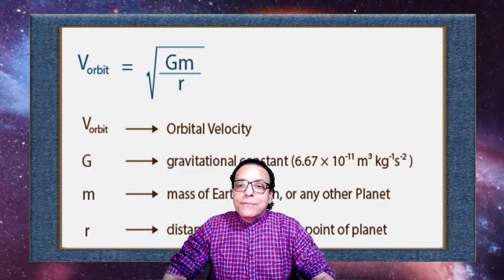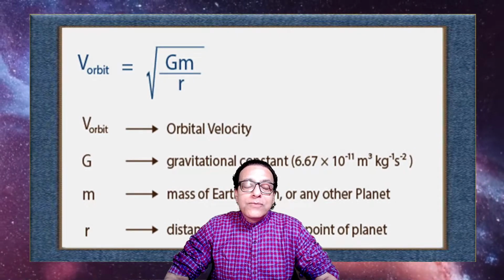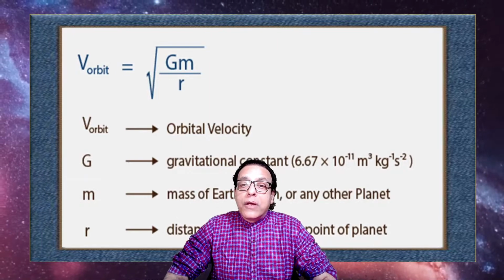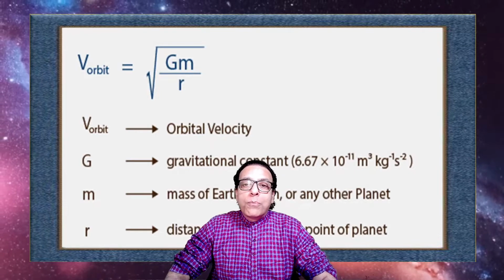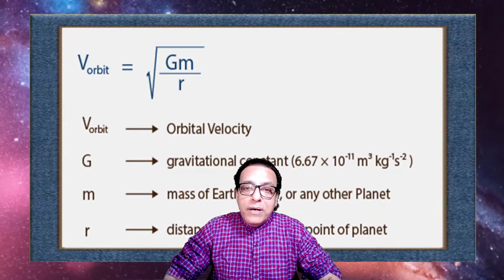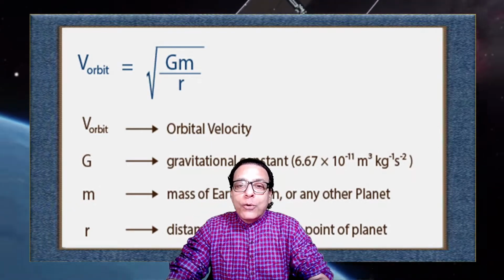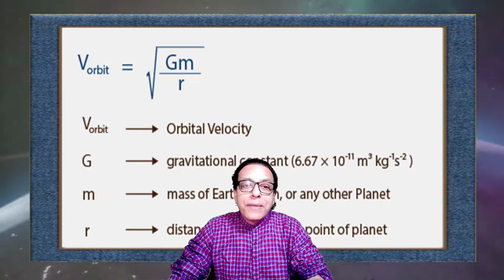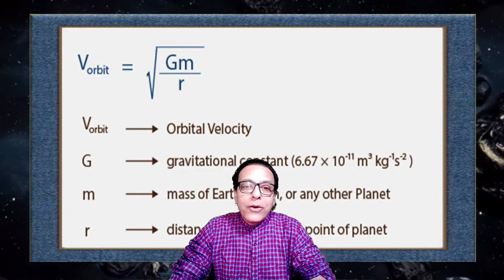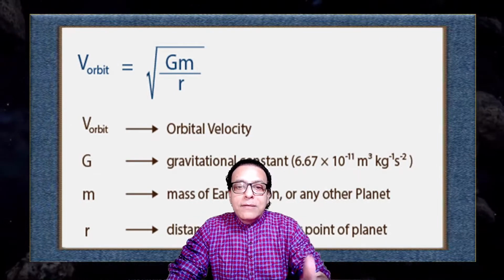And when you send a spacecraft into an orbit, you design this spacecraft with that intention, and at that height the spacecraft is supposed to do certain things. So you plan the whole thing, but the biggest obstacle is going against the gravity of the Earth, and that is where this formula comes in. This is a fairly standard formula, and this formula gives us the velocity required to reach a certain orbit. So if you want to reach a certain orbit, for example 100 kilometers above Earth or 300 kilometers above Earth, you know your objectives, and by applying this formula you can get the launch velocity required in order to reach that point in the orbit, because the other three parameters are constant.